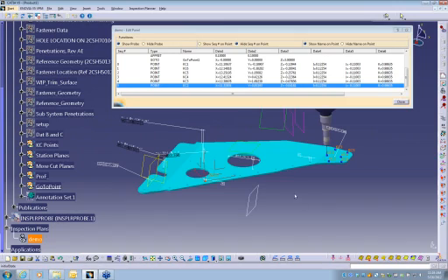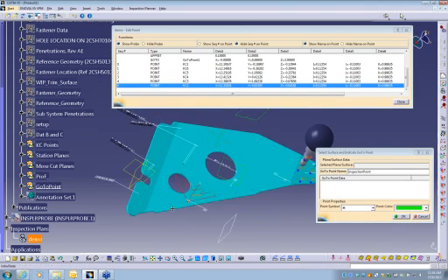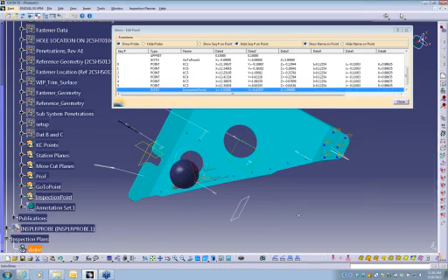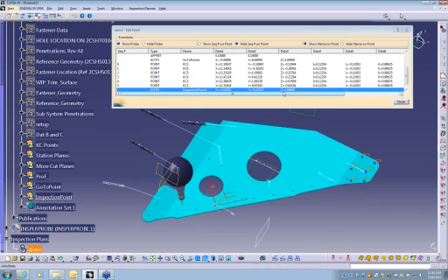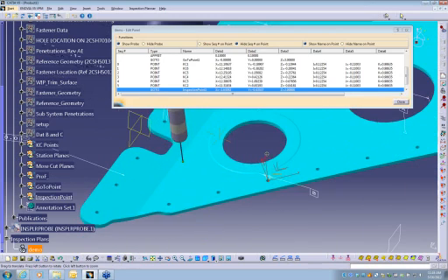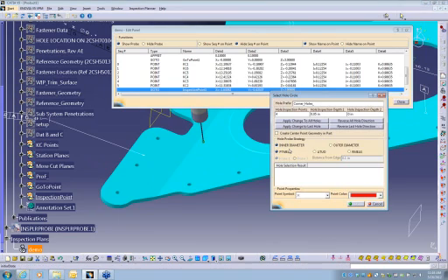Now let's say that we wanted to go through these holes right here. Again, we said that we have these different ways to do go-tos. This is a really fast way to move the probe around. I've never seen this in another software. We can actually pick on a plane in CATIA and indicate a point. So you can see that plane, that go-to move is at 2 inches. So we can go in here, and then we have these holes, and we have different strategies for holes. So this is a 2D hole.